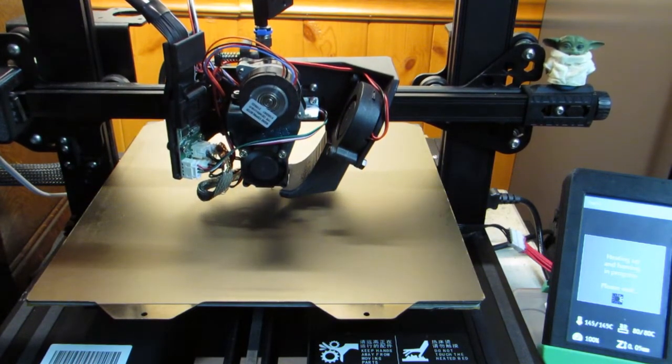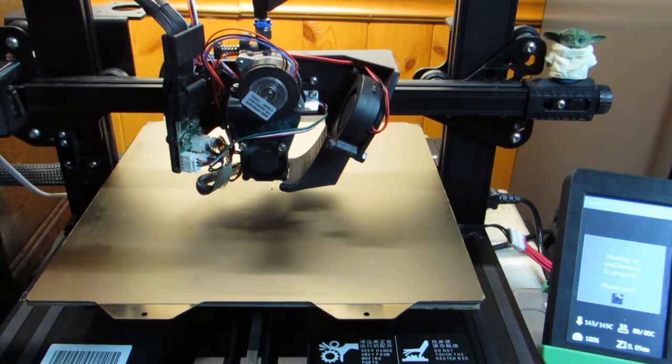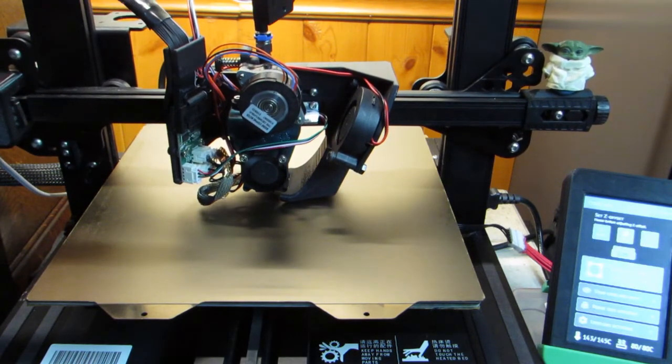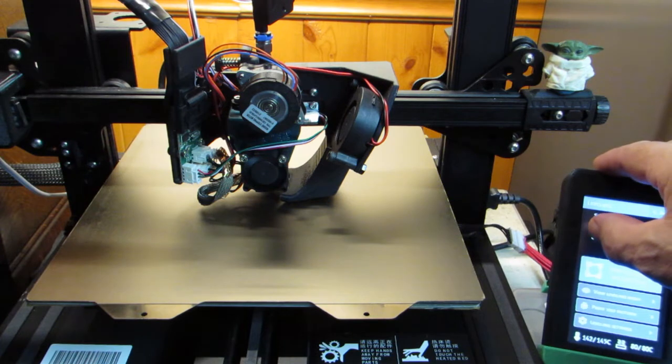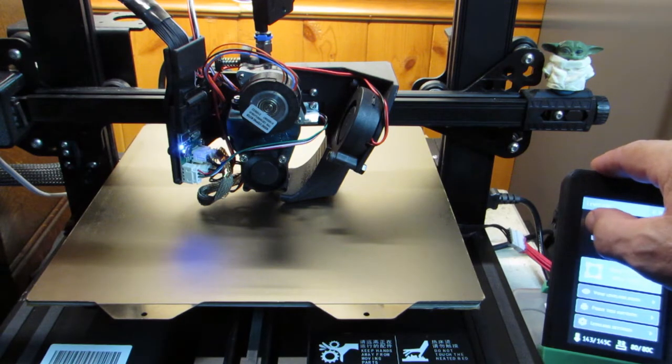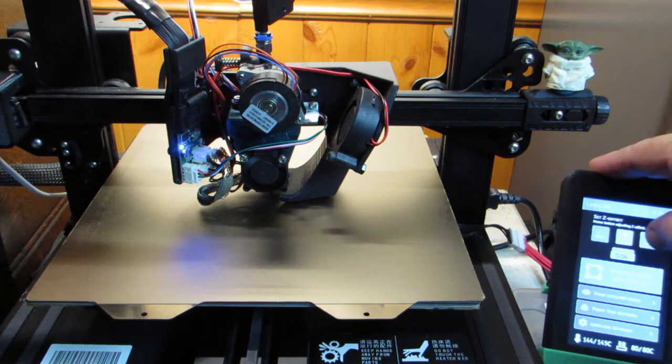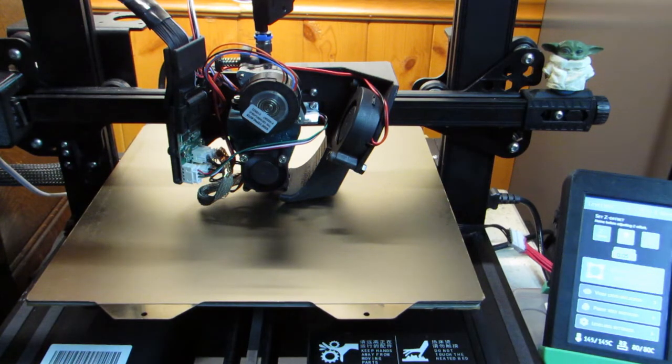Two measures, drops to 0. If we reduce the offset by 0.01, 0.02, lights on, 0.01 up, 0.02 up, lights off. So now we're at that other broader hysteresis value. Again, I don't know what makes the difference of plus or minus 0.01 versus plus or minus 0.02 in hysteresis. That's still an unknown to me.